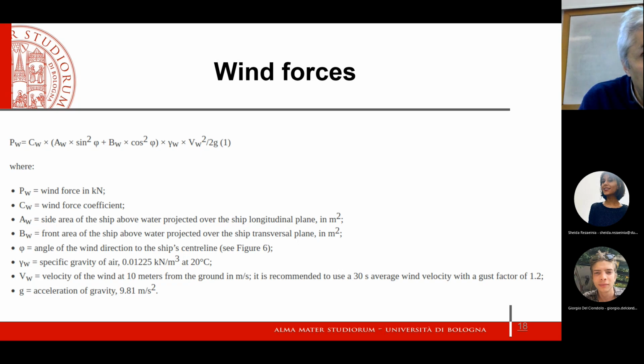So we have to find the area here somewhere. The wind force should also depend on the velocity of the wind squared, because we are engineers, we know that the pressure given by any fluid against a surface is proportional to the square of velocity. So we must find the velocity squared somewhere here.